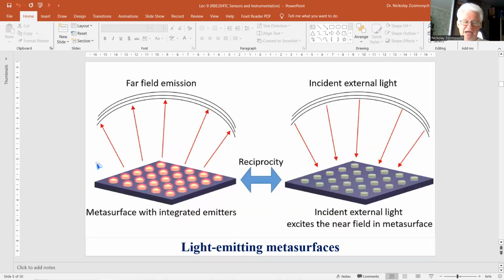LED, light emitting diode, a cheap and widely used light source for numerous applications, like illumination, displays, and remote control. Main characteristics are next: materials, gallium arsenide and others, maybe from III-V compounds, and a relatively narrow emission spectrum, tens of nanometers, covering all colors in the visible spectrum and infrared.